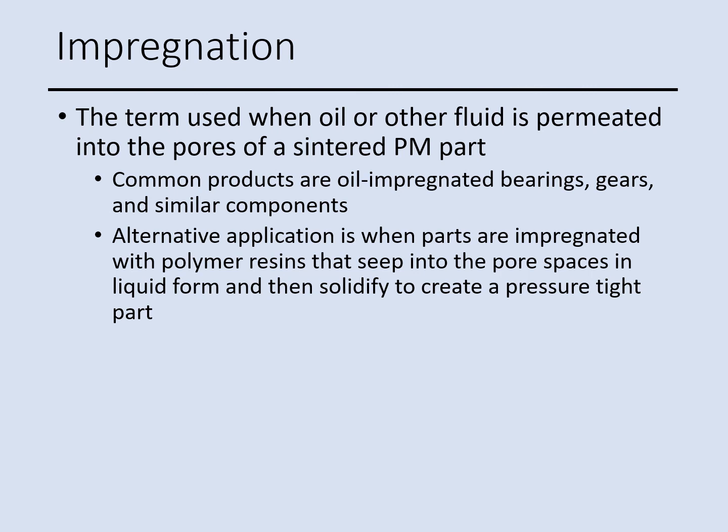Another application is when we use polymer resin in the powder metallurgy part. When the polymer seeps into the pores in the part, what happens? It's going to solidify. It's going to stay there, and it will create a tight part.